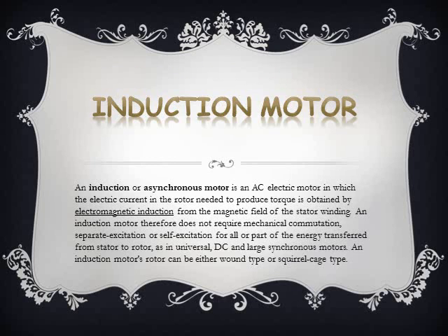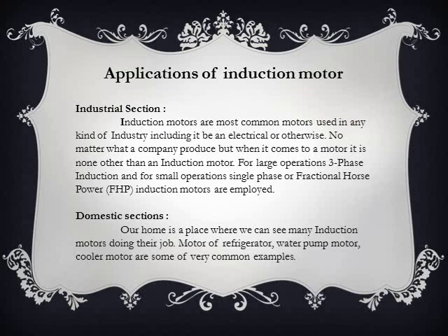Induction motor. An induction or asynchronous motor is an AC electric motor in which the electric current in the rotor needed to produce torque is obtained by electromagnetic induction from the magnetic field of the stator winding. An induction motor therefore does not require mechanical commutation, separate excitation or self-excitation for all or part of the energy transferred from stator to rotor, as in universal, DC and large synchronous motors. An induction motor's rotor can be either wound type or squirrel cage type.